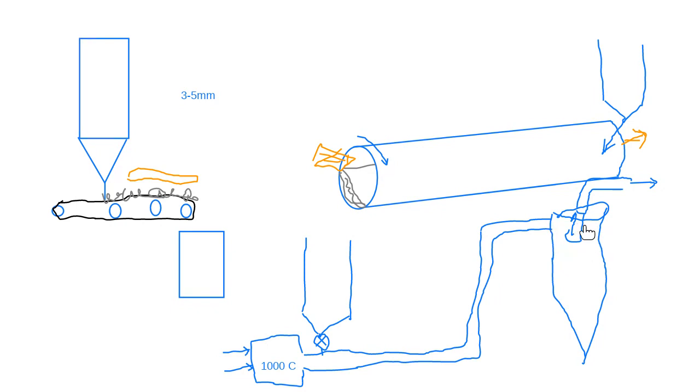So the particles and the gas are going around in a circle, and in fact there's an entire vortex that goes right down to the bottom, and eventually the vortex is not as strong at the bottom, and the particles all just slide down to the bottom, and they can be collected out here. And the flow of gas is such that it actually goes all the way down and then up the vortex, and this is nice clean gas that comes out. And cyclones are very effective. But anyway, what I've described over here is a pneumatic conveying system, or pneumatic drying system.